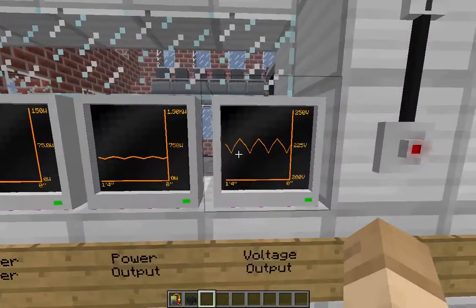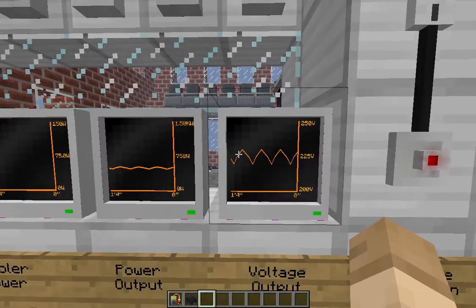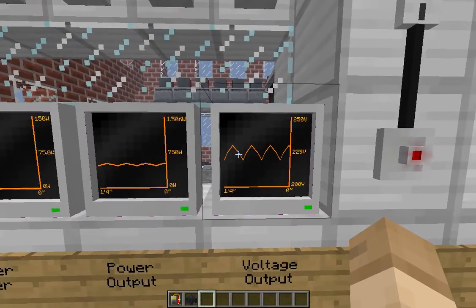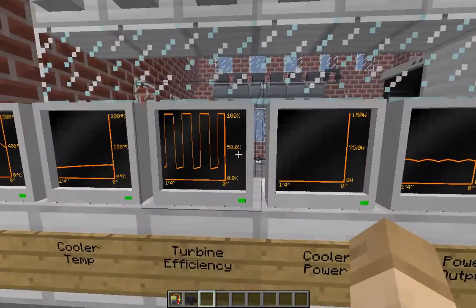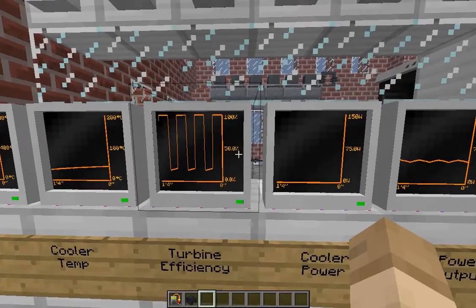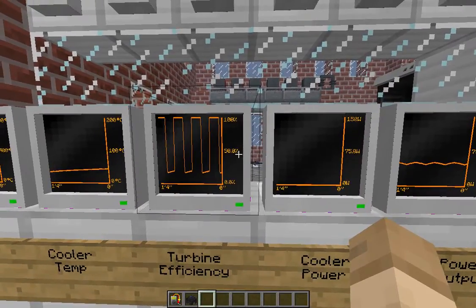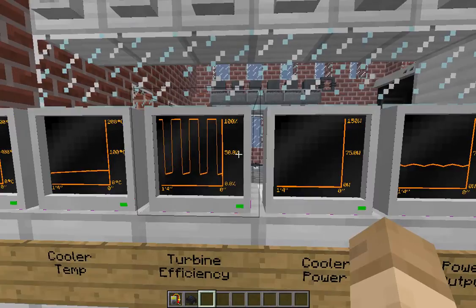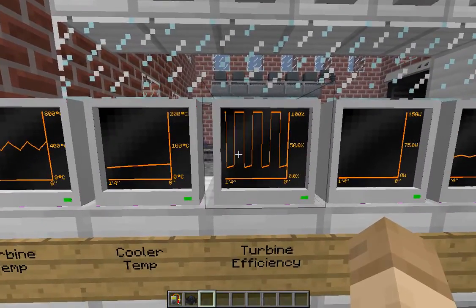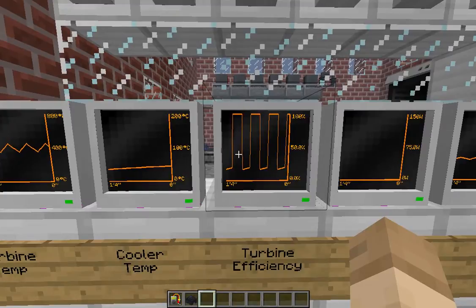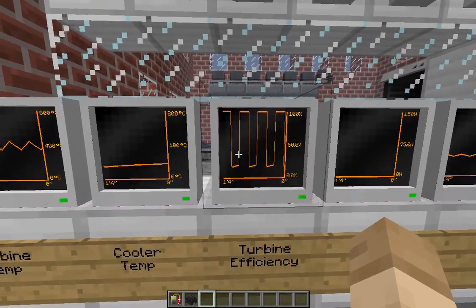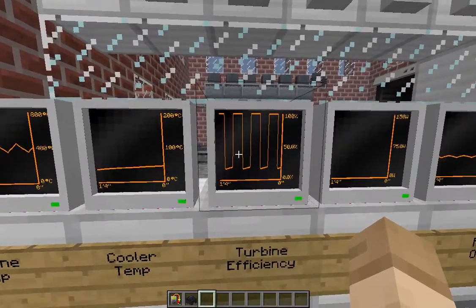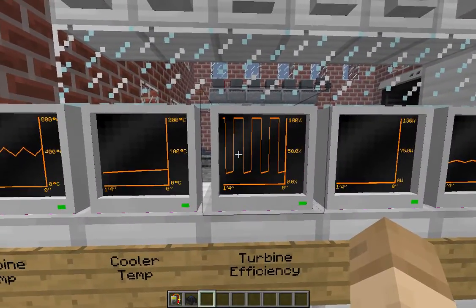This is also going to result in a little bit of a voltage hop, once you turn everything off, in that your voltage will still increase for a little bit. This is actually a good thing, in that if you make your range of voltage narrow enough, you can effectively overshoot your cap. So say you want your cable to be between 200 and 250 volts. That's a bad example. Let's do 200 and 230 for safety's sake. If you tell it to shut off and reduce power as it gets to 230, it's going to reduce it enough that you never reach 230.